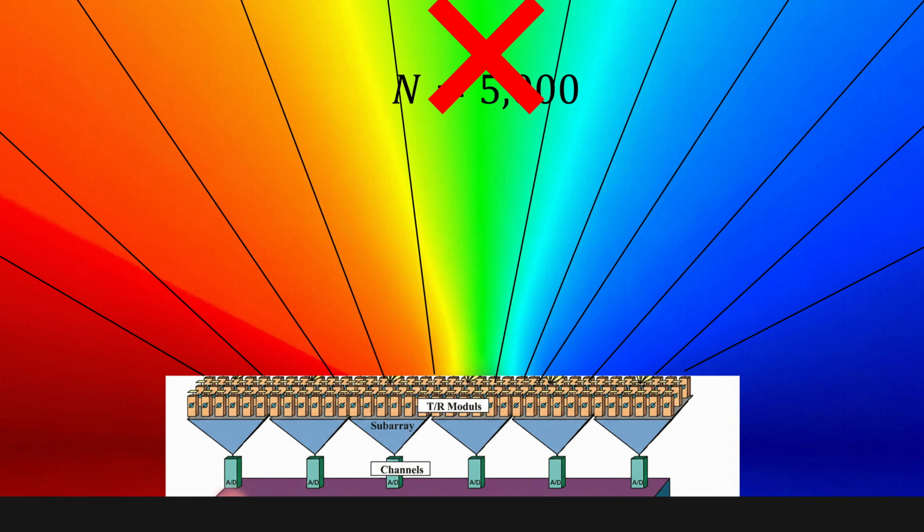Note that we cannot simply split the beam into hundreds of sub-apertures because each additional sub-aperture will require additional hardware plus exponentially more computing power for combining the beams. Also note that this effective PRF will not change the required PRF for unambiguously detecting very fast-moving aircraft because the Doppler shift that's induced by this will only be detected by one of these sub-apertures. So this upgrade mitigates the Doppler dilemma, and it allows for both better resolution and wider swaths in the azimuth direction. However, multi-channel does not decrease the PRF requirements for moving targets.